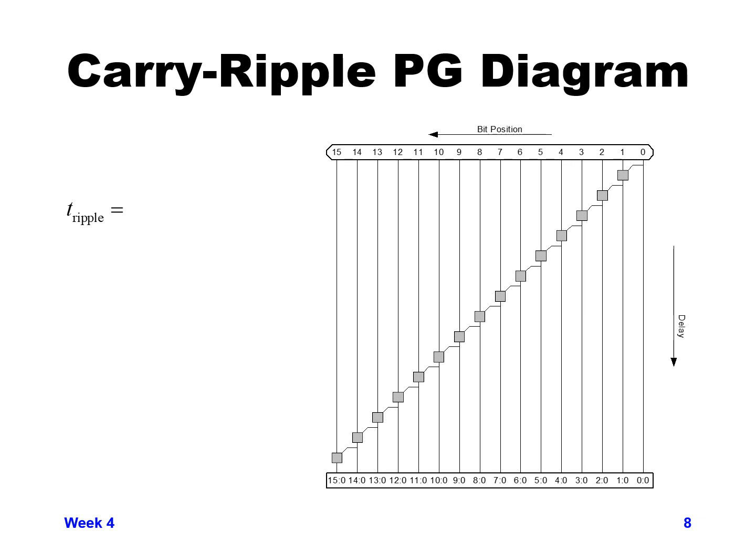On the right hand side, this is trying to show pictorially how the boxes are those PGK functions per bit, and then the connections show how at the output of a given bit you have the carry in go into the next bit, and so you propagate through. The Y dimension shows us the delay that you have going through each of those stages.